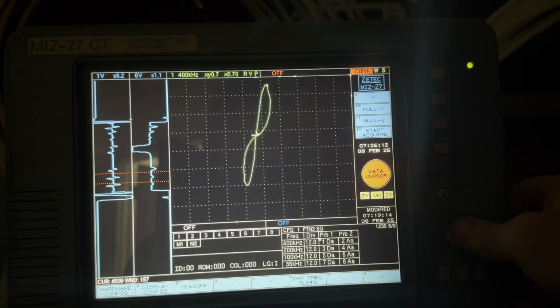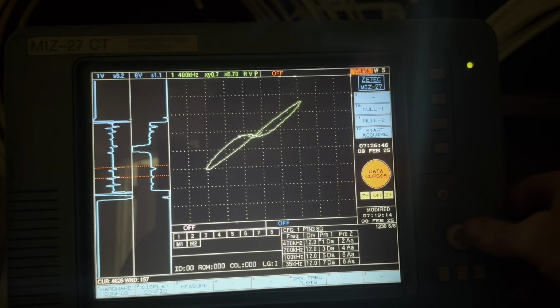It takes even longer for those disturbed eddy currents leading up to the 20% to be disturbed. So now, if you've got a bobbin ID probe and you're using 400 kilohertz, from the inside surface of the tube down to where the bottom of the 20% flat bottom hole is on the OD, that is the defective or flawed material from the 20% closest to the test coils. All the way down to that depth, the eddy currents aren't disturbed, but they start getting disturbed at the bottom of that flat bottom hole from the OD.